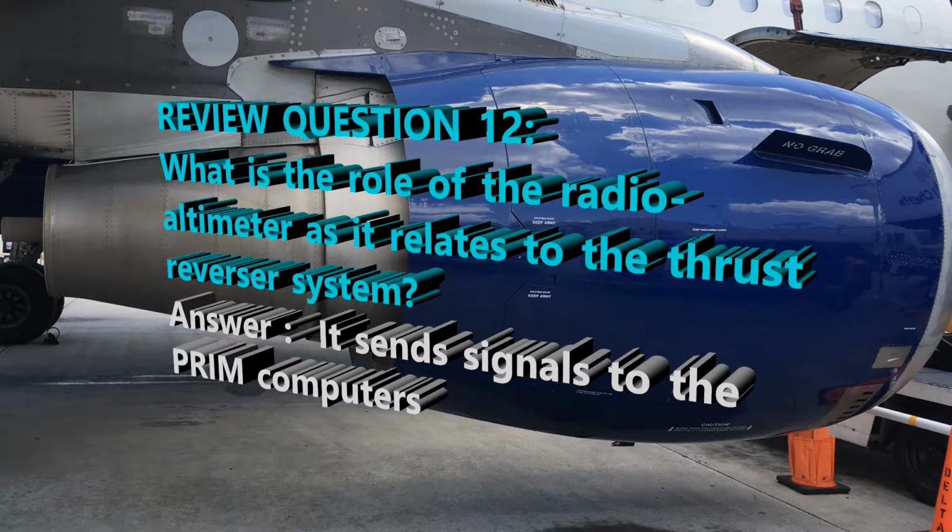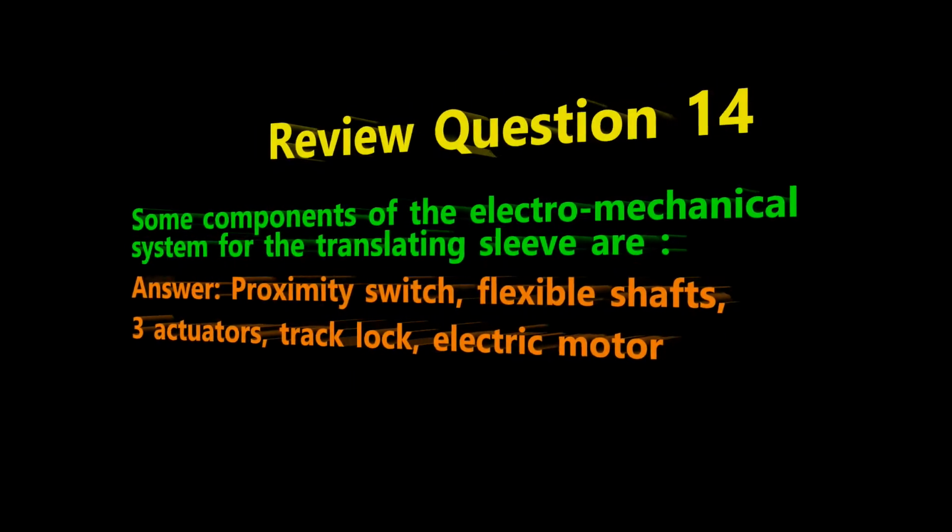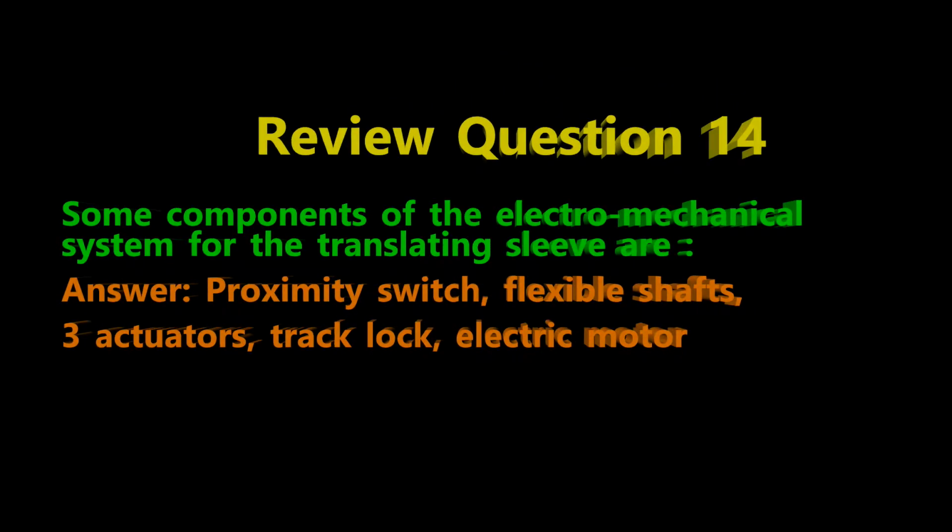Okay, now, number 13, the translating sleeve is a hydromechanical system. Is that true or false? That's false. It's electromechanical, not hydromechanical. Number 14, some components of the electromechanical system for the translating sleeves are: A, proximity switch, flexible shafts, 3 actuators, track lock, and an electric motor? Or is it B, proximity switch, non-flexible shafts, 2 actuators, 2 track locks, and an electric motor?